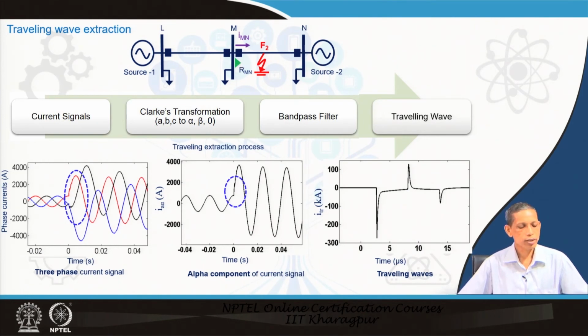From the current signals, we get the sample values to the data acquisition process, and as already mentioned, this is a high frequency component. Therefore, we need a high sampling rate, typically in megahertz, whereas in the normal phasor-based approach you talk about some 3-5 kilohertz.